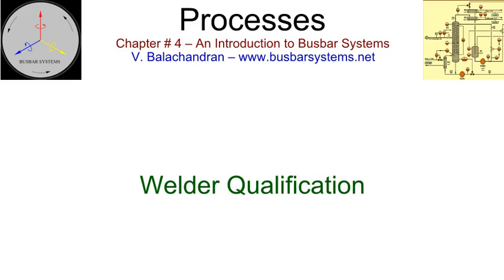Welder qualification. It is imperative to have the welders qualified and certified to undertake the work they are assigned. While a welder may be qualified from a technical institute, he has to be certified by an accredited agency for the specific type of work undertaken by him for his organization. Welders will have to be certified for steel, aluminium, and copper welding, and also for the degree of difficulty. The welders are to be monitored to ensure that they continue to possess the skill that they have been certified for.